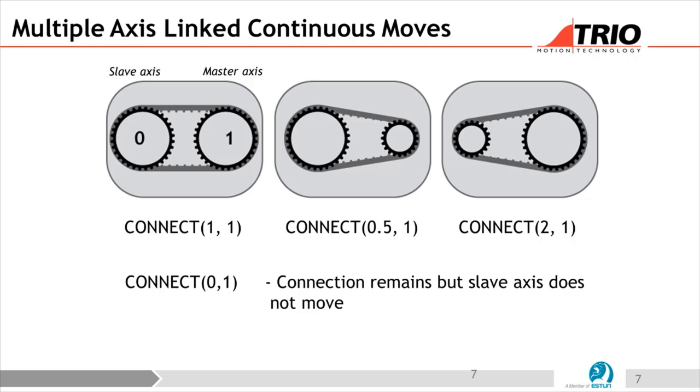If I've got an input axis, say the encoder on these modules is 4,000 counts per turn, and my slave axis is, say, an Eston drive with a 23-bit encoder, then one count on that wheel is not the same number of degrees of angle change as my 23-bit encoder on the motor. So in that case, I could probably use quite a high ratio, and it actually would be okay, just because I have this crazily high resolution on my slave axis.